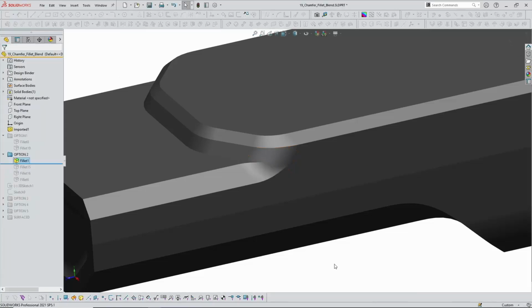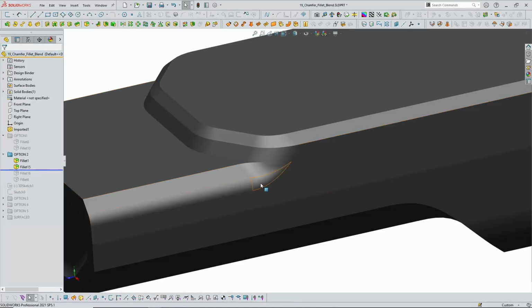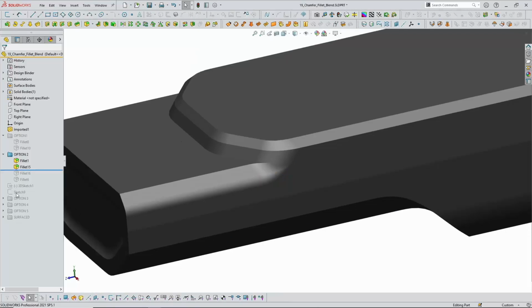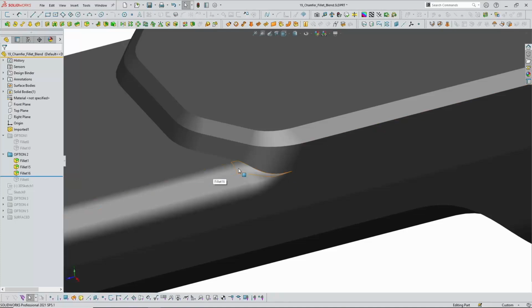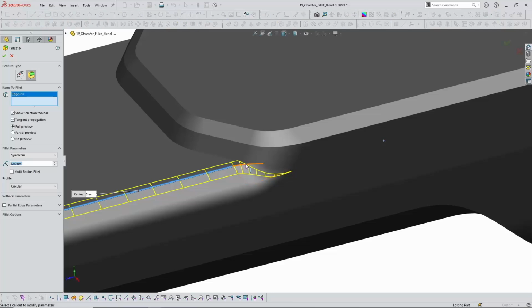And I now have a new transition surface, a slightly different set of edges. And when I go to add this fillet, I once again kind of get that taper effect that we had seen in the previous examples. And I also get this taper effect here. I can see this fillet starting to do some weird things as SOLIDWORKS tries to apply it onto this edge.